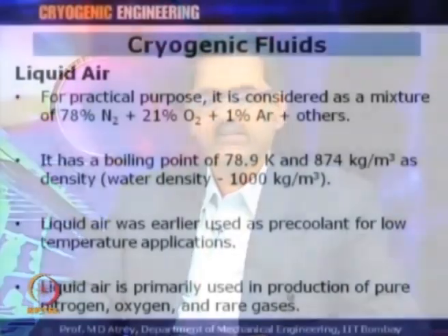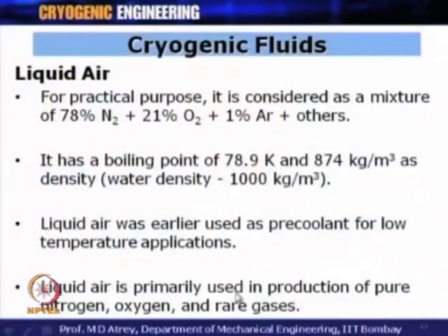So what I have to do first is to liquefy air and separate out these gases of nitrogen, oxygen, argon, helium, carbon dioxide, etc. by carrying out fractional distillation of air. But for that, what you need is air liquefaction. So you need an air liquefier, and this is a very big industry, and therefore liquid air is a very primary cryogen, I should say, for producing other pure gases like nitrogen, oxygen and all other rare gases, which you can basically find only in air. So this is one of the very important cryogens, and also liquid nitrogen, which is primarily used everywhere in cryogenic engineering.